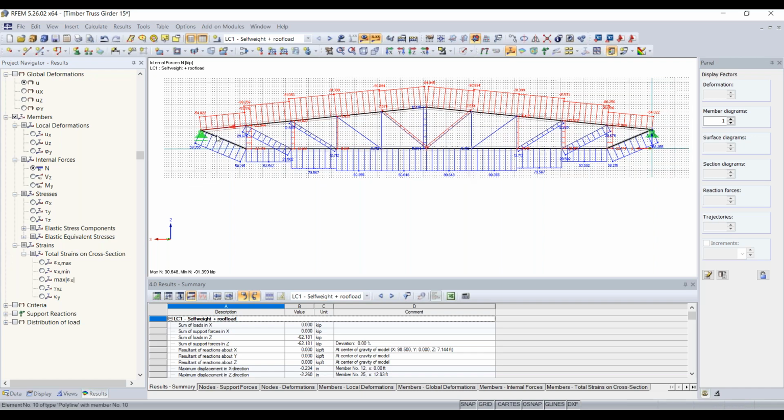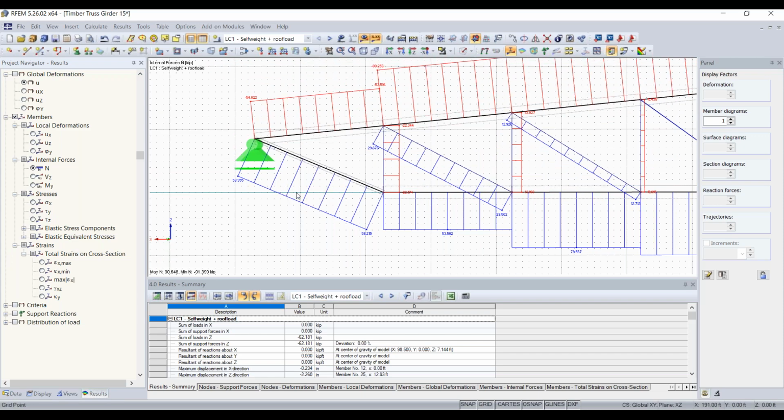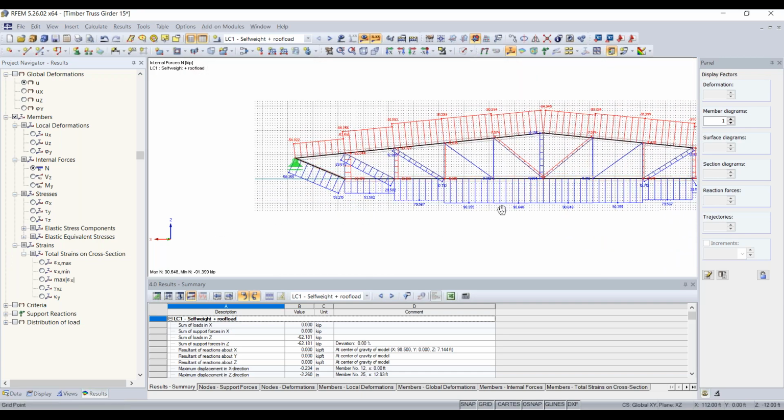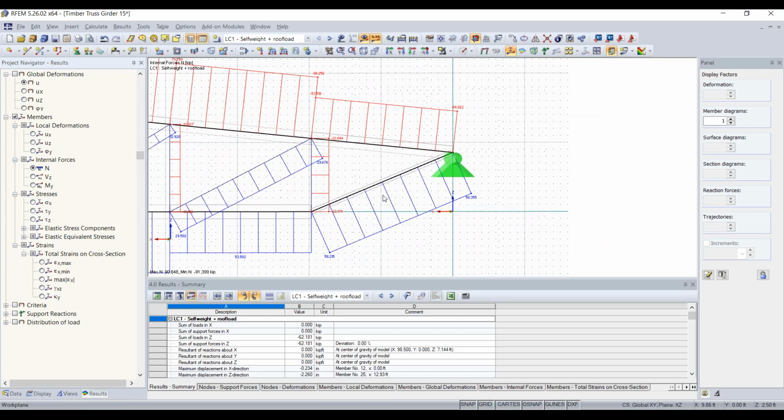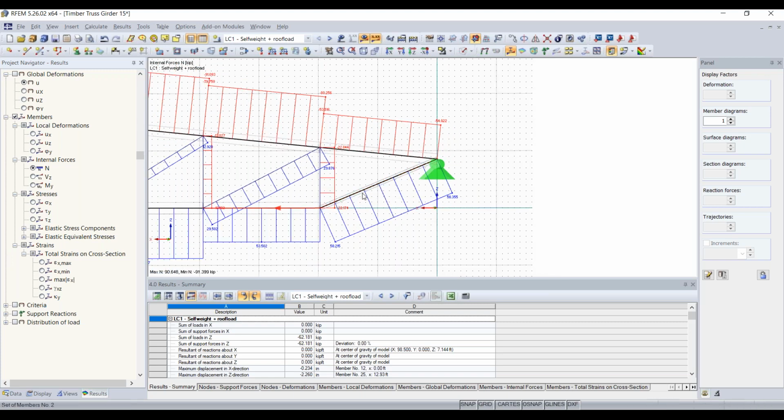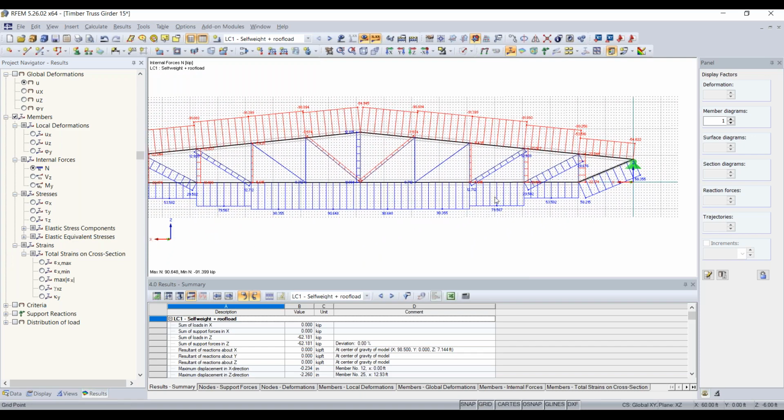You can also see something important to point out: we have very high forces on our outside diagonal members here, which I did on purpose. I can show you later how to optimize these, since these will be critical members. Their cross section is a lot smaller than the main cross sections that we created for our bottom chord here, and they don't really compare too much in size with the bottom chord and the tension forces that it's receiving.